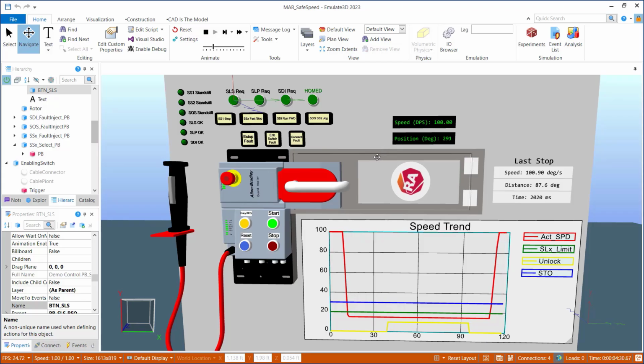Well, 10, 15 years ago, before safe speed, I would have had to lock out and tag out that machine. I would have had to stop production, get my power turned off, all sources of energy turned off, go to the lock, and put a lockout tagout tag on there with my name, and then possibly scrap product, and then rethread the needle, and then restart and rehome. It could have taken 30 to 60 minutes on average for me to perform that simple task with lockout tagout as my only tool.